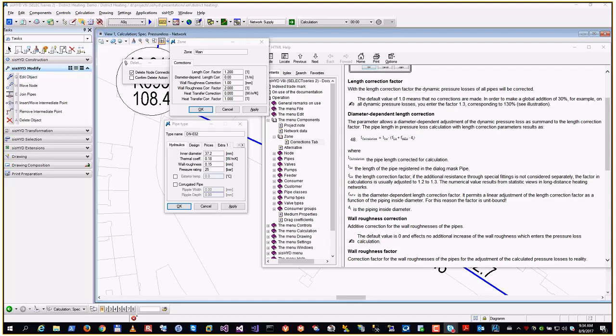I know that the district heating organization in Germany has statistics, and they tell that this factor is between 10 and 20%. It depends: if it's a transportation line, it's a bit lower. If it's an area with a lot of consumers and a lot of bending of pipes, it is higher. If you really do this comparison between measured results and the computational model, what I learned from one of our users is that it is most important to get the heat loss computation correct.